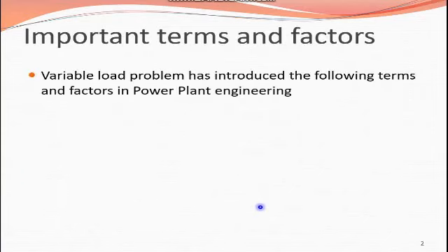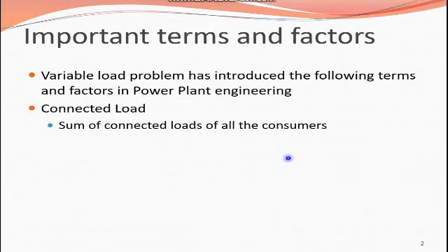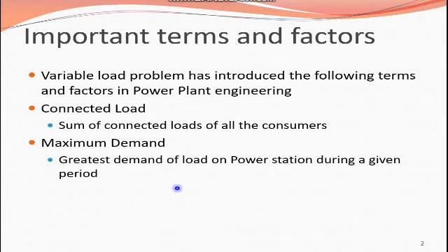A few more terms. Variable load problems have introduced the following terms and factors in power plant engineering. Let's start one by one. So what is connected load? Sum of the connected loads of all the consumers. What is maximum demand? Greatest demand of load on power station during a specific interval of time.